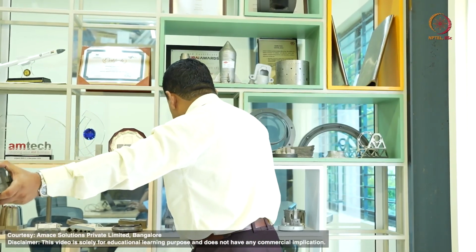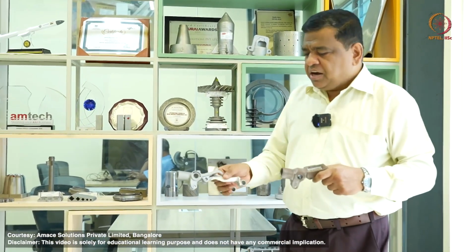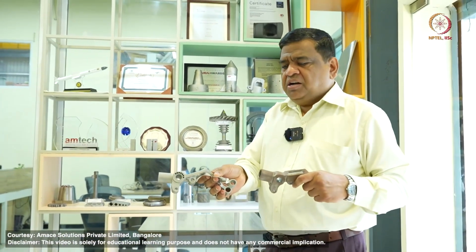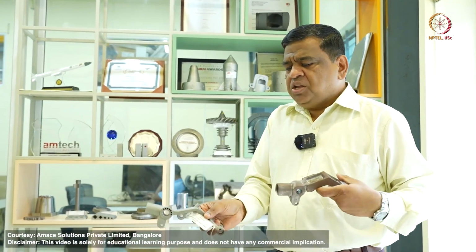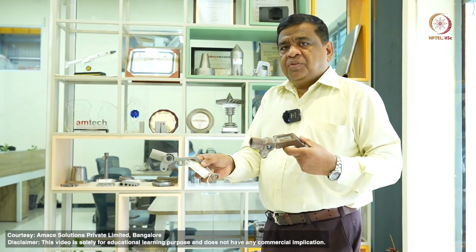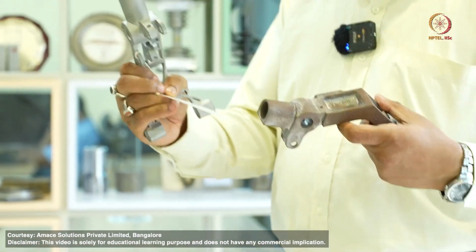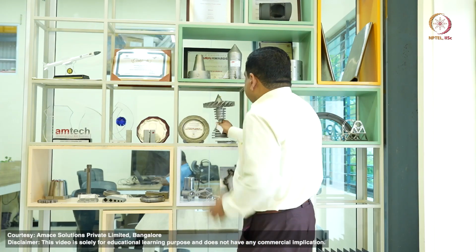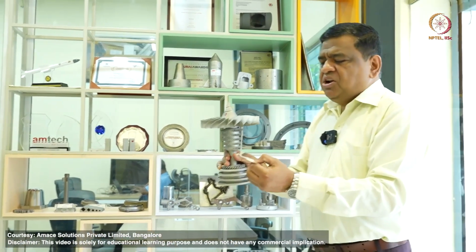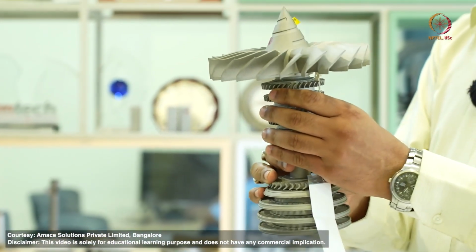I am going to show you, this is the original structure, and this is the same structure designed using the topology optimization process. You can see that one of the major advantages of topology optimization is weight saving. This is now made of aluminum 10 silicon magnesium alloy, and this is also used for tool holder applications. This one is the same material, aluminum 10 silicon magnesium alloy, and this application is for aerospace.